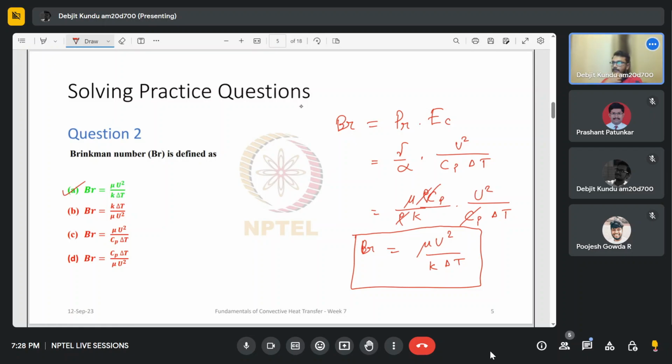So in case Brinkman number is much greater than 1, that would mean that the viscous dissipation is actually significant, and dissipation has to be considered, which is often ignored when it is not important. So determining whether dissipation is important or not can come from the scaling of this Brinkman number. This is how it guides us towards a correct way of problem solving.